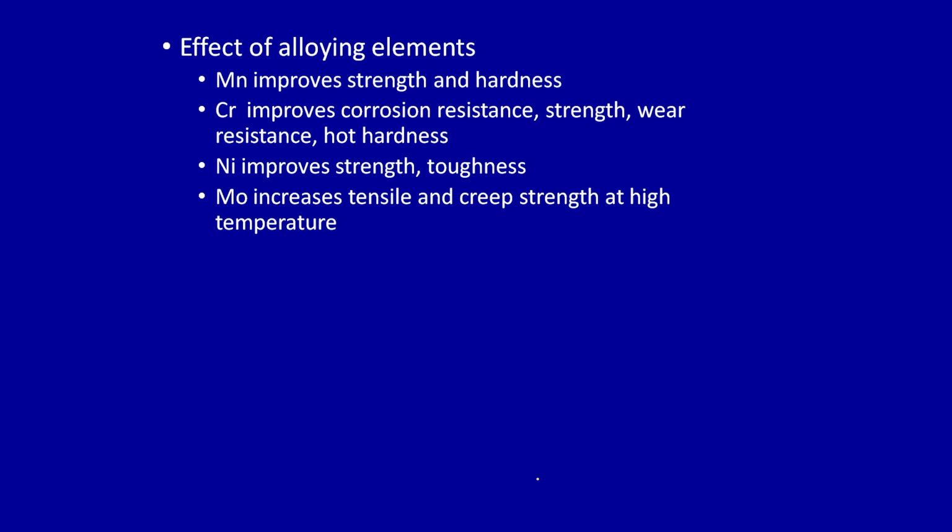Chromium improves corrosion resistance, I already talked about it. It also gives you strength, wear resistance and hot hardness. Nickel improves strength and toughness both. Moly increases tensile and creep resistance, and keeps strength at high temperature.